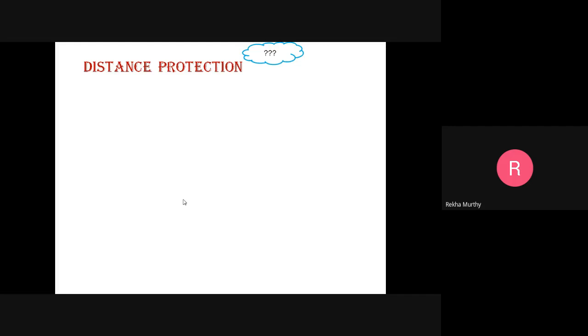Modern distance relays usually provide very high speed fault clearance. They are used where overcurrent relays would be very slow, and where grading time overcurrent relays is very difficult for complicated networks. That is why the distance relay is employed for the protection of transmission and sub-transmission lines in the range of 220 kV, 132 kV, 66 kV and 33 kV. Sometimes they are used at 11 kV.